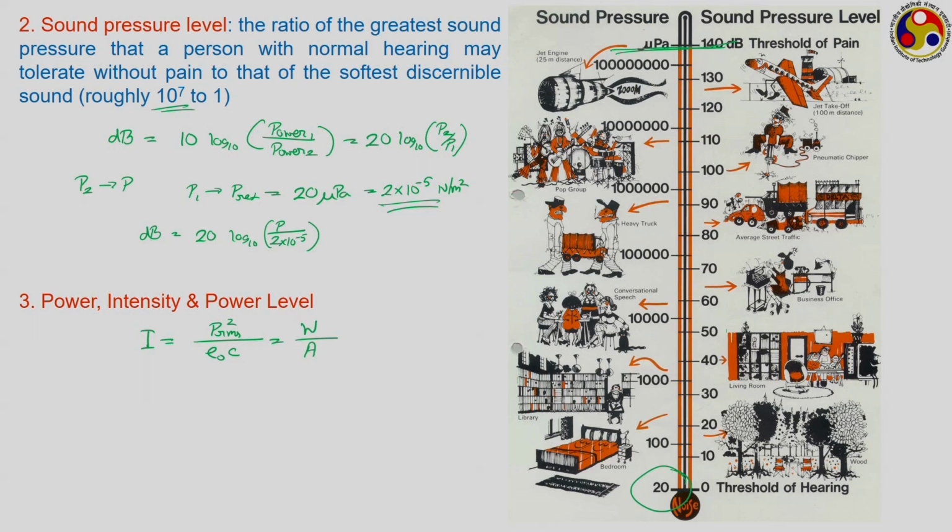So, W is the acoustic power, which is proportional to P RMS square, as we have used in the previous one also. Again we need to choose a certain kind of reference if we want to represent this in terms of some decibel. We generally do not represent intensity in terms of decibel, but the power is often represented in a decibel form, just similar to this particular ratio.